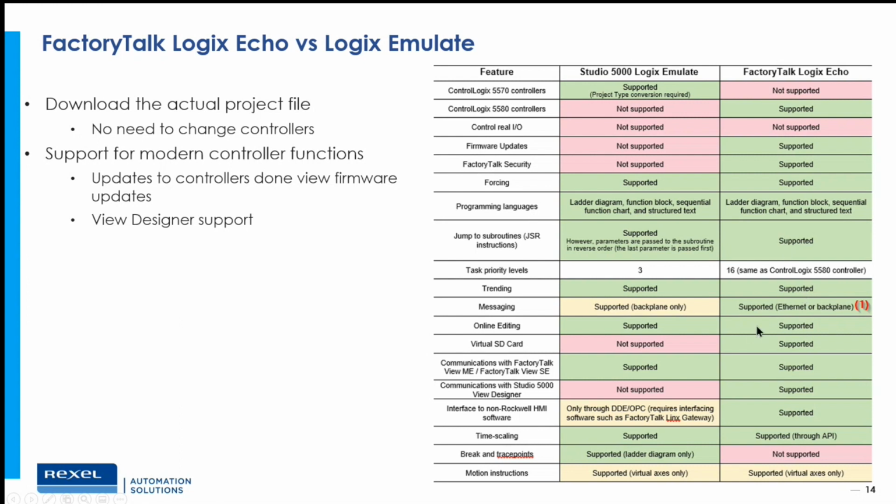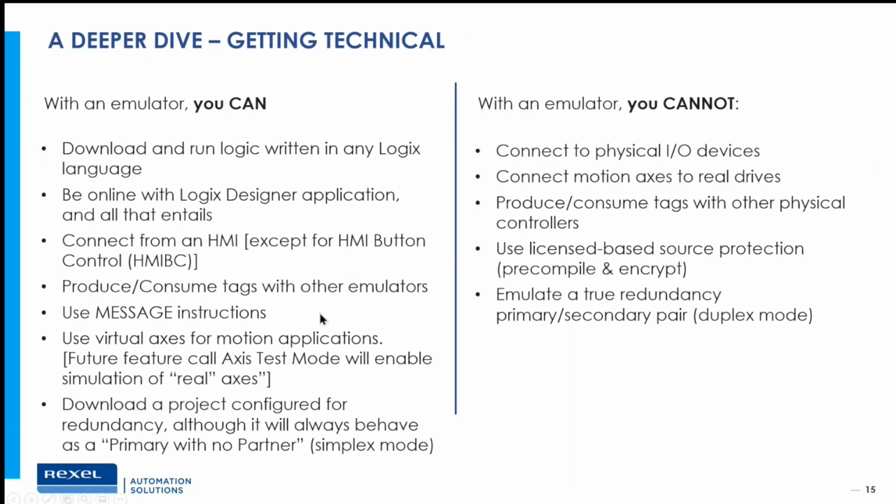Moving down the list here, just picking out some items of interest that I see. There's the virtual SD card, communications with View Designer, and here's that interface to non-Rockwell HMI software. You could kind of do it before with Logix Emulate using the DDE OPC topic, but in this case, it's more of a seamless integration. So motion instructions, it's still only going to support virtual axes only. There is a future feature coming on, and I think I talk about it in a later slide, so I'll wait till that comes up.